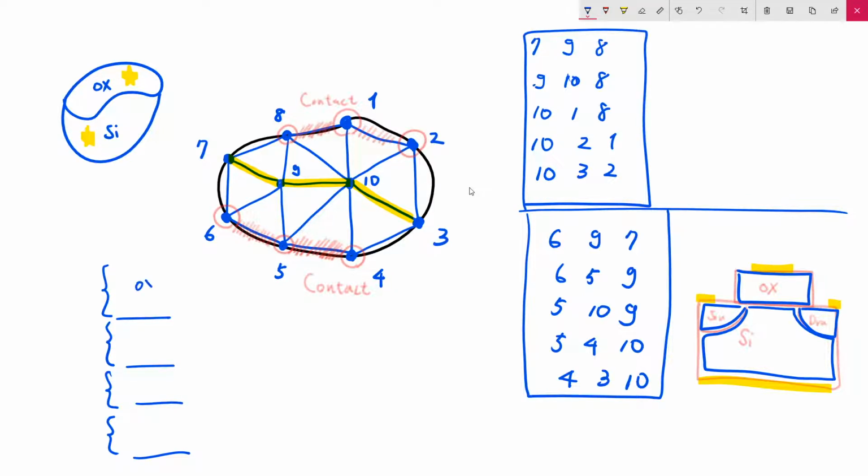For example, this is for the oxide region, and this is the source region, and this is the silicon substrate region and the drain region. Then that will fully specify your complicated system. So usually, that is not mandatory, but usually people try to build just one file specifying all regions